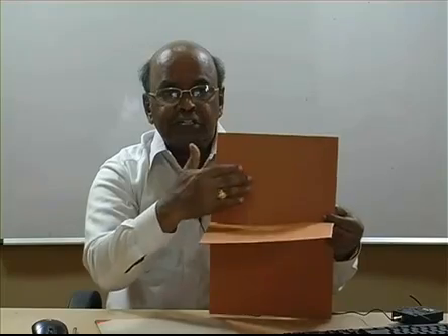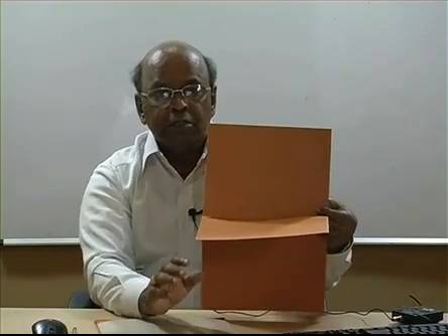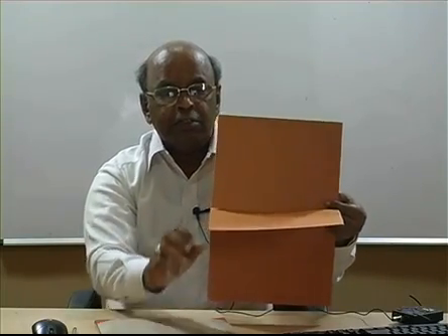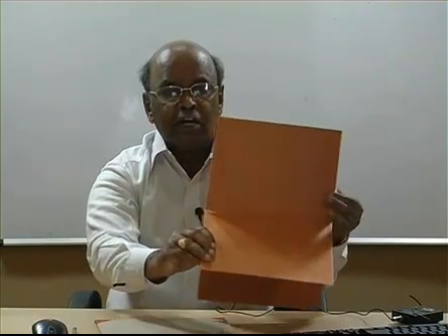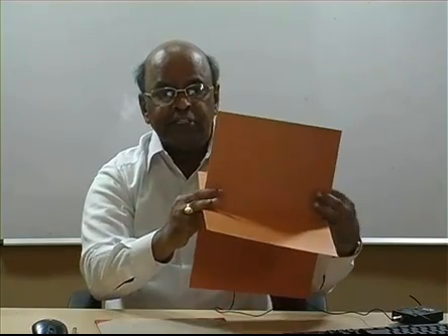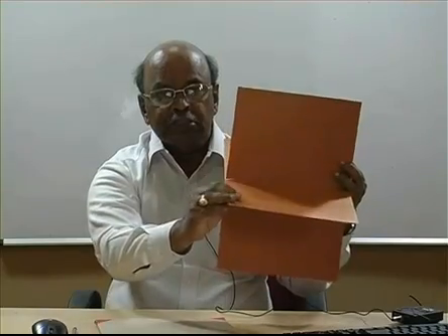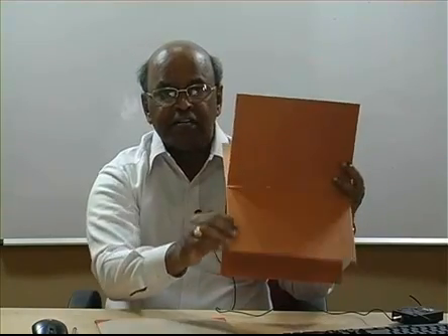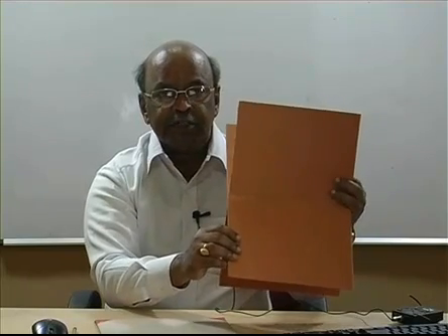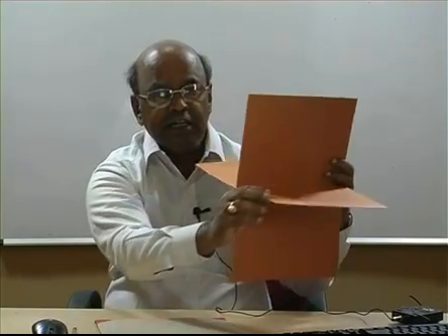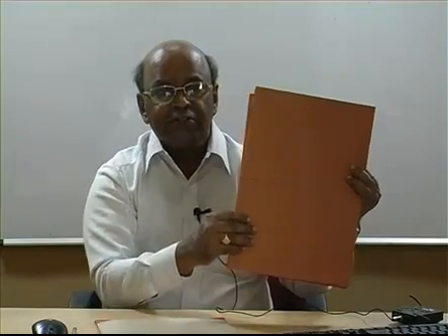So these two projections on two different planes, to draw on the drawing sheet, you should rotate this horizontal plane always such that first quadrant 90 degrees becomes 180 degrees. So this direction of rotation of the horizontal plane is always the same irrespective of the object, whether it is in the second, third or fourth quadrant. So accordingly, as the plane rotates, the projection on it also rotates.